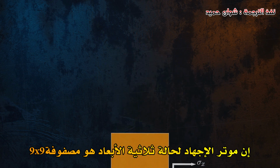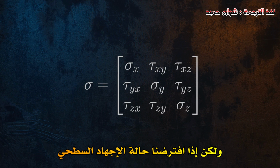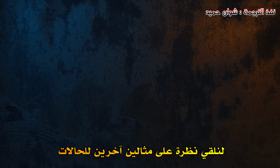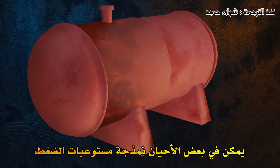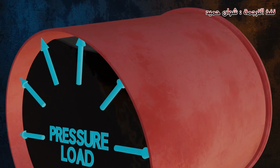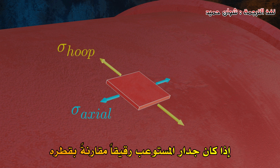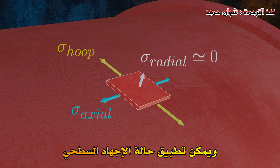The stress tensor for a 3-dimensional case is a 3 by 3 matrix, but if we consider plane stress conditions, it is reduced to a much more manageable 2 by 2 matrix. Let's look at 2 more examples of situations where it might be appropriate to assume plane stress conditions. Pressure vessels can sometimes be modeled using plane stress assumptions. The pressure load generates hoop stresses, which are oriented around the circumference of the vessel, and axial stresses. If the vessel wall is thin compared to its diameter, radial stresses will be close to 0, and plane stress conditions will be applicable.